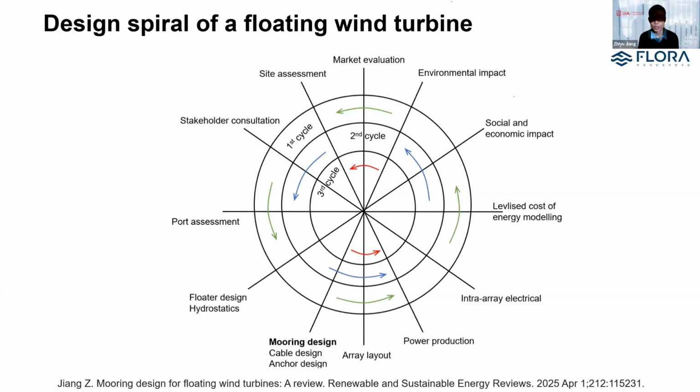Site assessment is usually carried out at a very early stage. We need to know the potential wind resources as well as metocean conditions. What will be the dominant environmental loads, right? The dominant wind direction, wave direction, current loads, etc. So there's a whole bunch of considerations that we need to account for at the design stage. And this mooring design is just one piece of the spiral, and there can be several cycles that we need to do. Okay, it's not that we just do the design in one fell swoop and it's done. It's not like that. We need to have a lot of iterations with other different tasks.